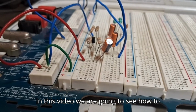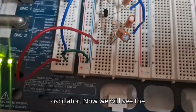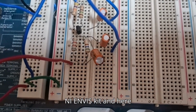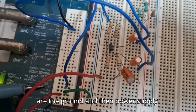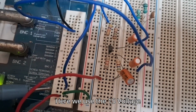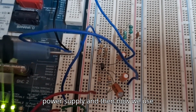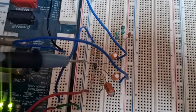In this video, we are going to see how to design the CE amplifier and Hartley oscillator. Now we will see the connections of an amplifier. This is the NI ELVIS kit, and here are the ground and then the power supply. Here we use the 15 V power supply, and then we use the BC548 transistor.